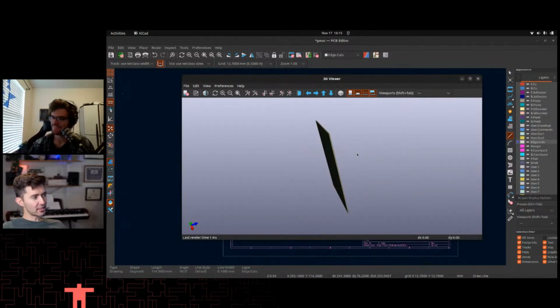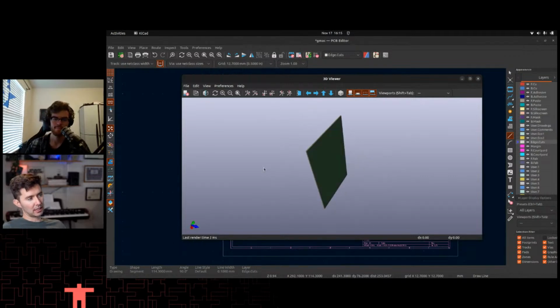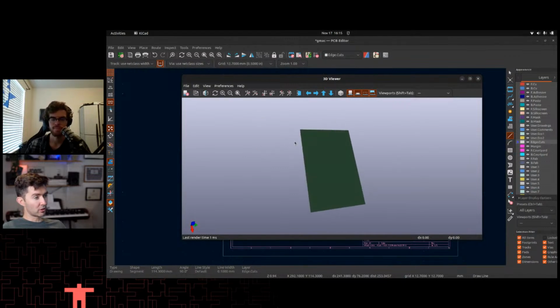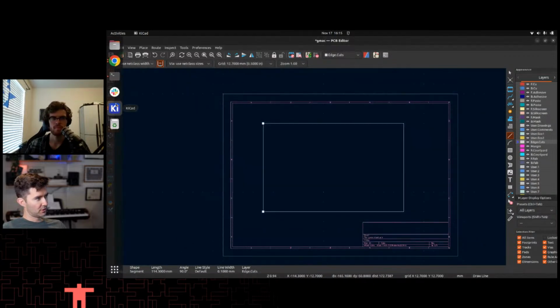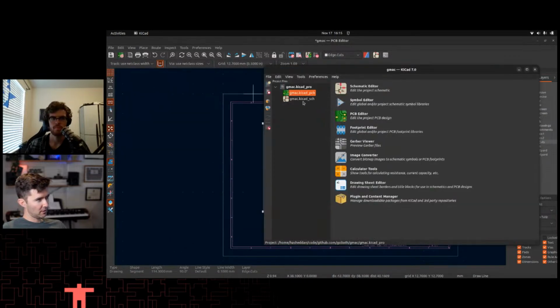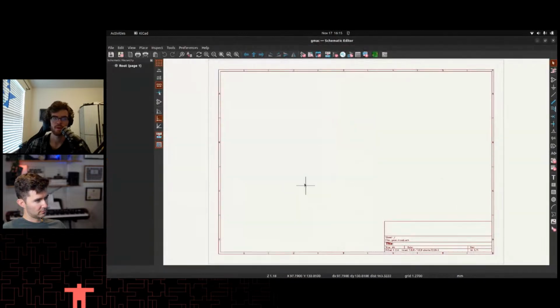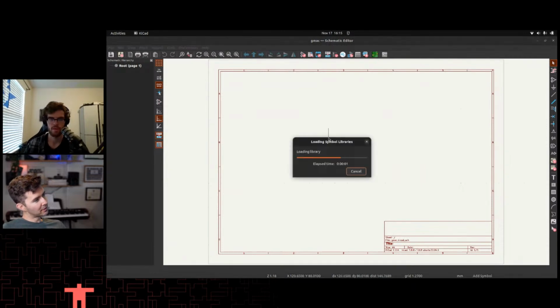Oh, man. So another thing that's really important, I feel like on a lot of boards, that took me forever to add in, is mounting holes, right? One thing we could do is go to the schematic real quick, and maybe that would be where we wrap this up for now. Is there a better way to open it than that? Right. And then you can hit O and click. This is just the same dialog as the third button down on the right. Oh, sorry, it's A on the schematic. Sorry, A. There you go.